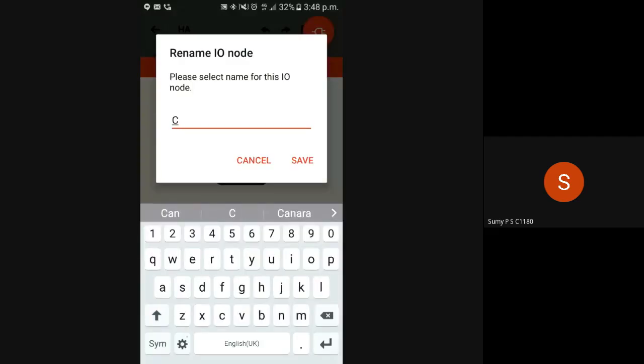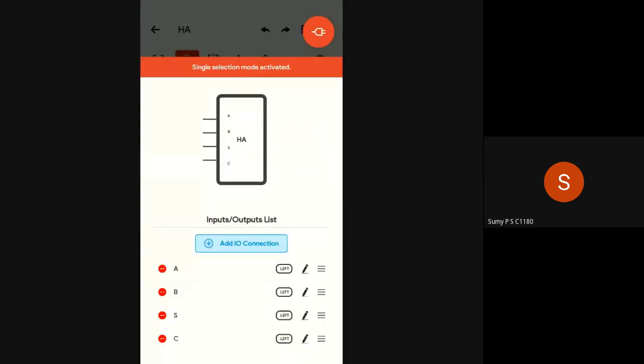Can you people type? What about the orientation of the outputs in the given diagram? It is on the left side. Whichever side is better. To which side I have to move the sum and carry so that the block looks proper? Yes, Jeevitha. So to move it to the right side, what is next to S? Left. You click the top and change, click again, it becomes right. Similarly, carry. Is it okay now?